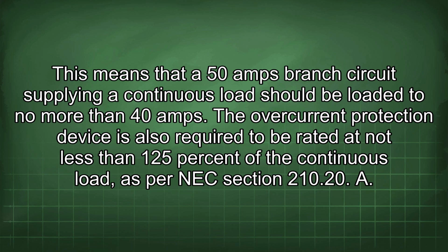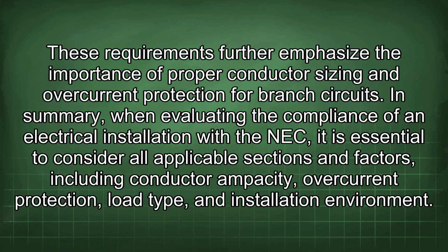The overcurrent protection device is also required to be rated to not less than 125% of the continuous load, as per NEC Section 210.20. These requirements further emphasize the importance of proper conductor sizing and overcurrent protection for branch circuits.